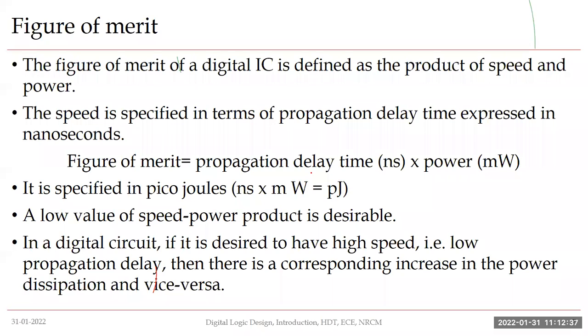Why is this particular value, the figure of merit, important? You will see in future that the propagation delay time and power are often complementary to each other. So when we try to improve the propagation delay, that means making the device run faster, we will end up spending more power. And if I try to save power consumption, I may end up with a circuit which is very slow in nature.